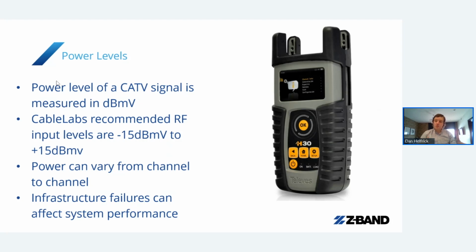If you have more traditional infrastructure, though, if you've got a coax system, let's say, and you've got a trunk and tap platform rather than a home run platform. You're bringing that coax up the riser, you're tapping off. Maybe you've got some splitters in your infrastructure. Maybe there's an amplifier, and then somebody reaches up into the ceiling to give themselves television, and boom, now you've got a splitter that you don't know about. That's going to change your power, right?